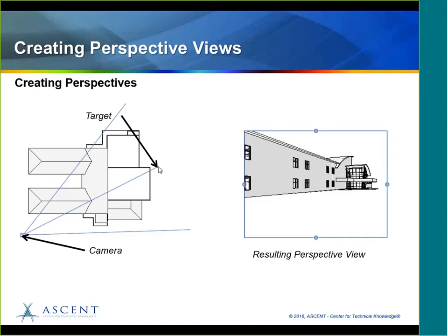So first of all, remember to do perspectives. And there's a few things that you can do in perspectives that you used to not be able to do. And that includes things like you can pin and unpin. I forget exactly which one came in 2017, but you can do a line, move, and copy, cut or paste from the clipboard. So there's a number of things that can happen in perspective views that you do need to be aware of.